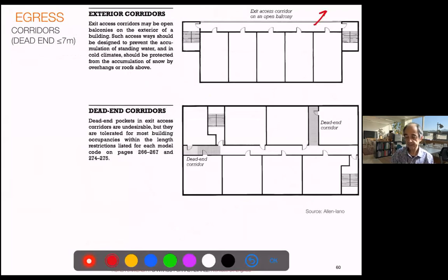Exterior corridors are great because they always have air and give much protection. So that stair is very unlikely to be affected by the fire of any unit. But that means that all the doors should have some kind of fire resistance. You have to avoid dead end corridors as much as possible, right? If you have them, you need very clear signaling, so it doesn't happen as it happened in Seoul last year, when people got lost and couldn't find the exit because they didn't see the signs. So they just suffocated under the smoke.